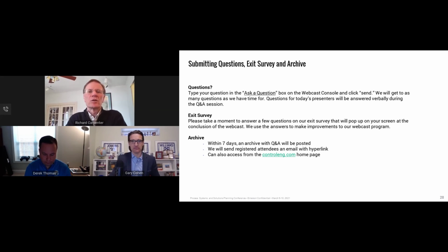Another good question. I think you start with the data that you're familiar with. Usually that's some type of process data, especially if you're down at the edge, because you're really talking about data that's collected from machines and sensors. Sometimes you don't know where those correlations are going to be, so you look at what's available. Sometimes the machine is having a certain type of problem, and you don't have enough information to troubleshoot it, so you add instrumentation to the machine to be able to get insights relative to that problem. You bring that into your edge device, and a lot of times, just through simple trends, events, alarms, other mechanisms, you can very quickly start to understand, oh, I see what's happening.